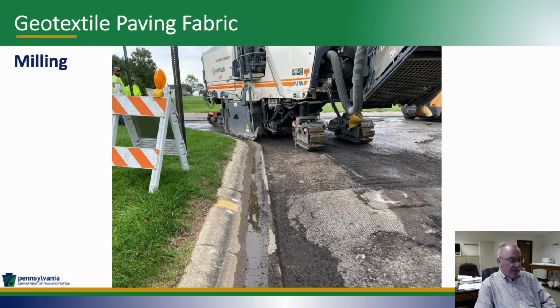In this section here, the contractor was required to mill along the curb line with a 6-foot wide milling head. They milled 1 3/4 inches deep along the curb line and 0 inches deep near the travel lane. The millings were hauled to the township building for use on another future public works project. The contractor then was required to sweep the road after the milling operation.